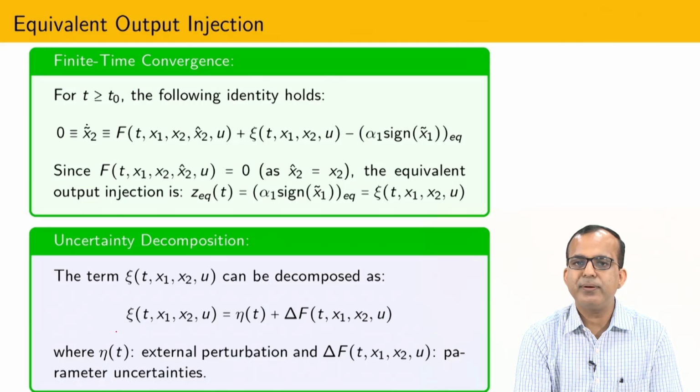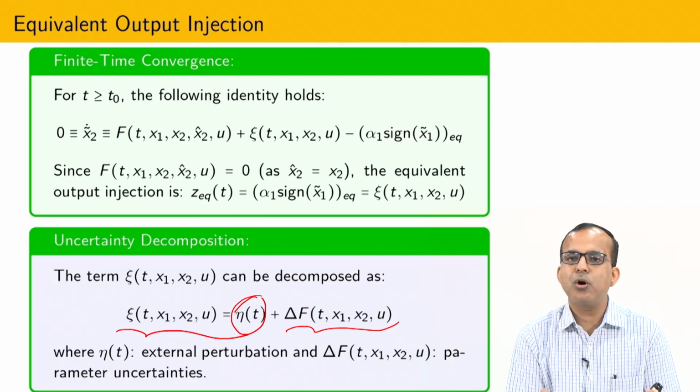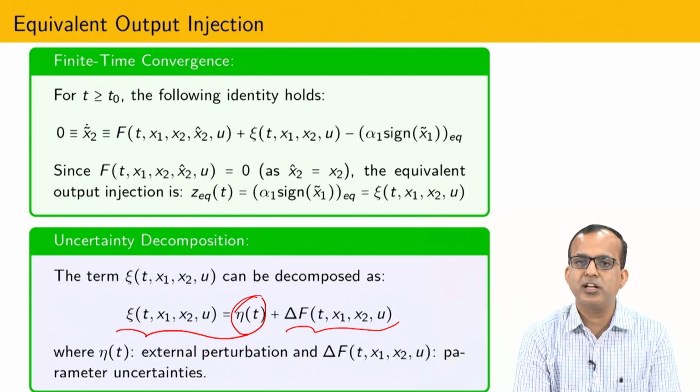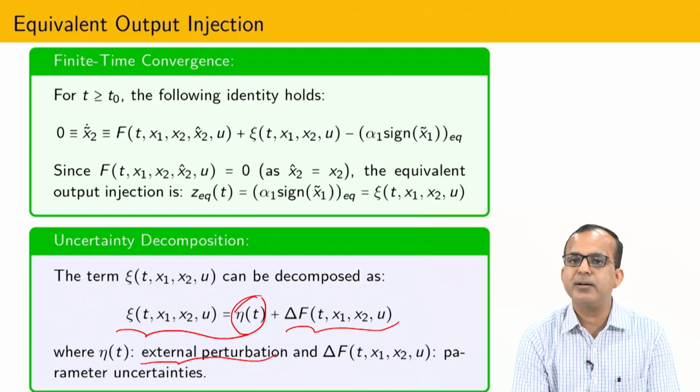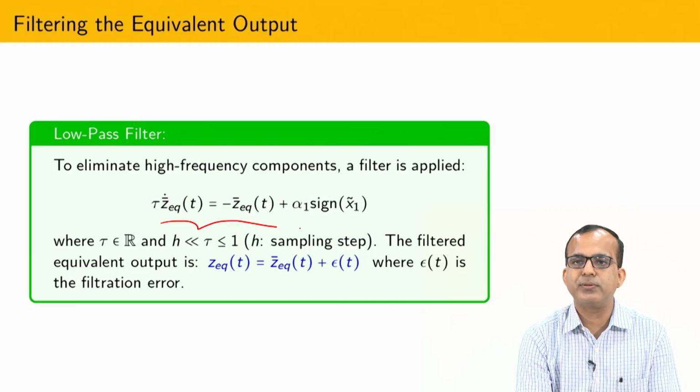So basically whenever we have this system, I can decompose it into an internal uncertainty as well as an external uncertainty, and most of the time the fault is coming from an external source, or some kind of attack is coming from an external source. So you can easily get that attack, or the form of signal which is attacking your system, by passing through the low pass filter.